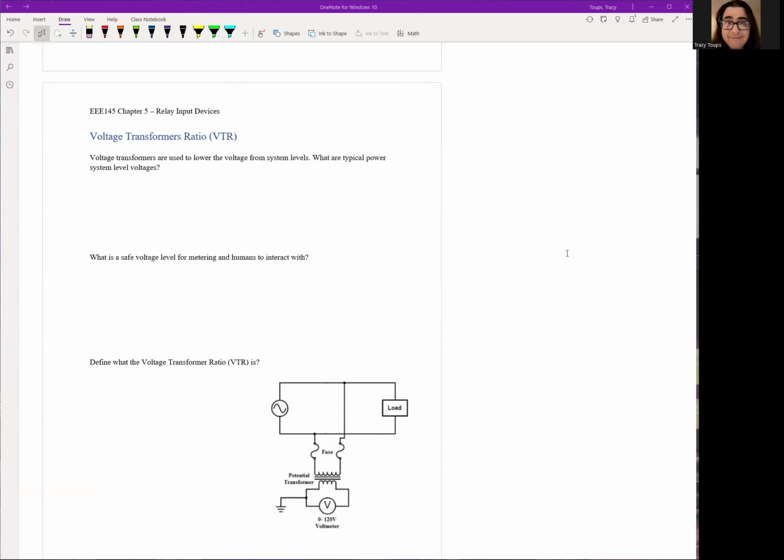Typically, you want lower voltage and lower current levels, because then the actual meter itself can be made smaller and it'll be cheaper. We technically could make a meter directly to connect to a 115 kV system, but it's going to be really, really expensive because of the insulation we need to build into the meter. It's much easier to use a PT to bring it to instrumentation level voltage and then just run a bunch of meters off of that.